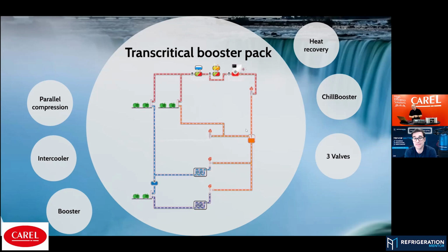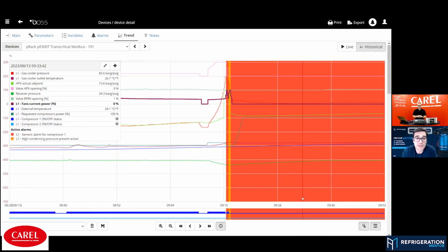That's the part. Yeah, I love that. It's so true, because the more I learn, and I continue to learn about CO2 and commercial refrigeration, the more I understand each and every component inside and out, it makes me understand the system as a whole, because one moving part can affect 3 or 4 other things. It's kind of like the compressor. I do compressor trainings all the time, and the compressor takes the punishment of 90% of the components in a system. Right. We see the compressor, oh, that's the problem, but really it's something else in the system. So you want to really take your time to understand each component.